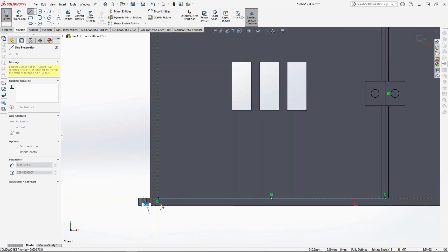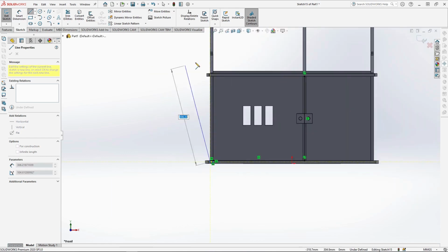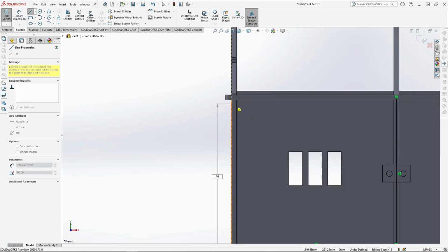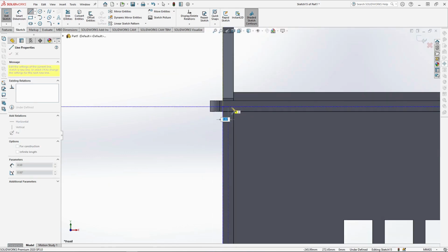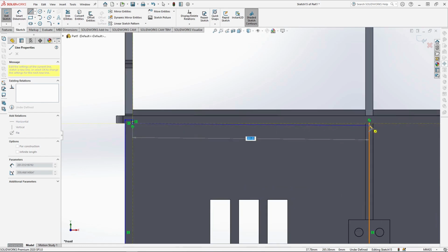To add the door's pivot points, go down by 4mm, across by 9, then up by 267mm. Go across 9mm at the top and 4mm down to do the top pivot point, and join it up to close the profile.